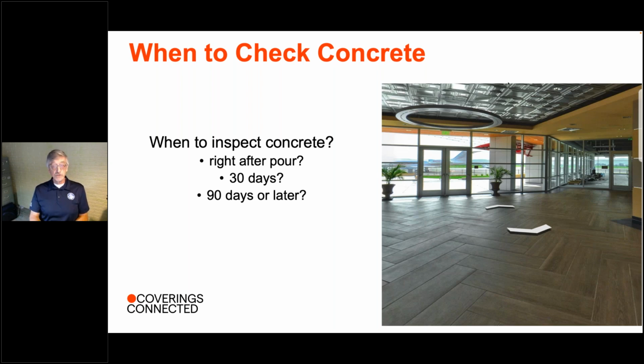They brought their 10-foot straight edge and lasers, and they checked that floor for flatness, that substrate, and they found it wasn't flat. So they went back to the general contractor, the architect, specifier, the owner, and they said, hey, look, we can't install our large format tile, our 12 by 48 inch tile on here without having the substrate prepped to be flat to tile industry standards, because it won't end up being a flat finished installation.